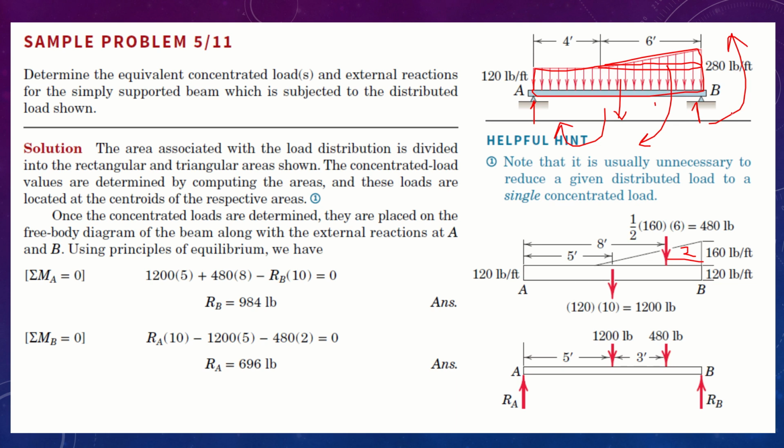This is going to give you two equations. Or rather than saying the sum of forces acting along the y axis equals 0, you can generate a secondary moment equation, which this person has done. He took the second moment equation saying sum of moments about point B is equal to 0. You're going to get the answer, but two unknowns in two equations are more than enough. Now, once you solve this, I hope you'll get the values of RB and RA as shown here. This is a very, very simple question.